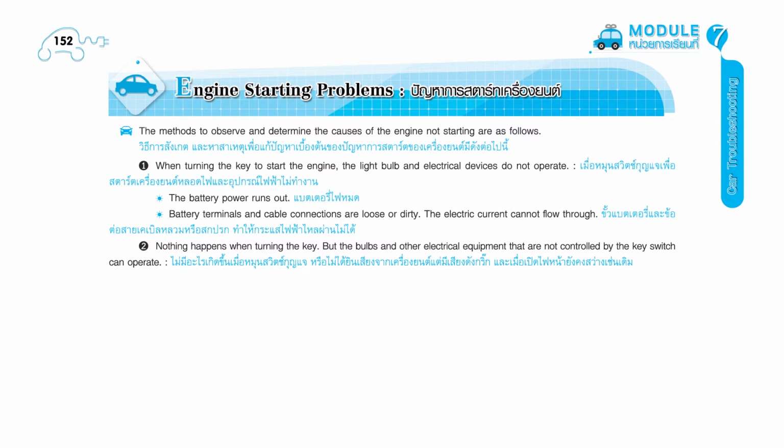2. Nothing happens when turning the key, but the bulbs and other electrical equipment that are not controlled by the key switch can operate. Key switch is defective. Ignition fuses are defective.